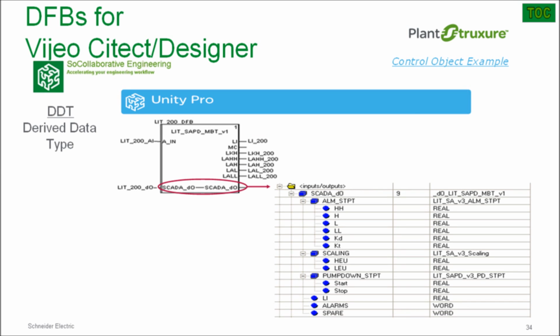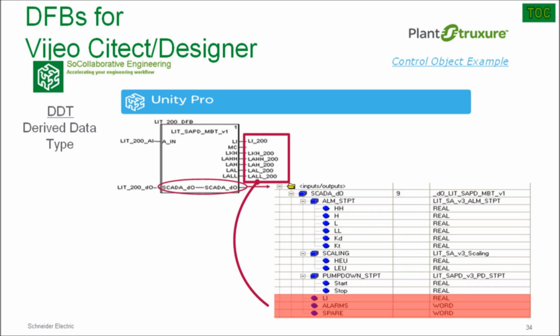Now back to the comparison. Another difference between the Modbus version and the OFS OPC version can be found in the SCADA data object. The output pin variables of the OFS OPC version will provide duplicate data to elements contained in the SCADA data object of the Modbus version. So these elements should be deleted from the DDT for the OFS OPC version of the DFB.